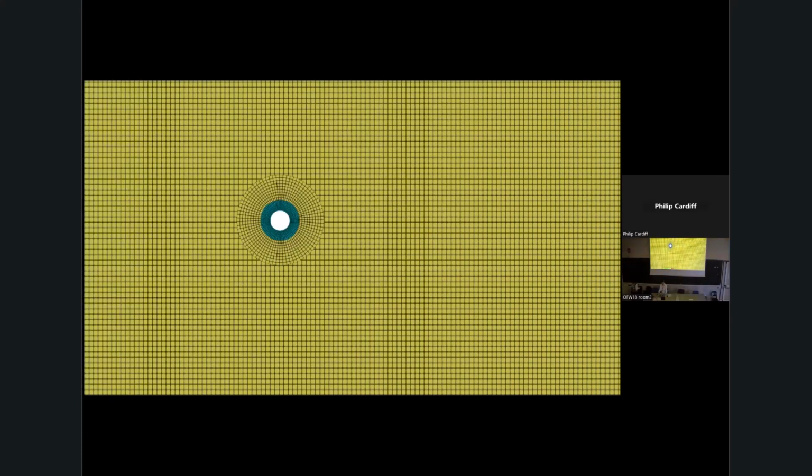Just to show an example with preCICE, and you can find this on the website, I took overPimpleDyMFoam, I think they call it. It's the overset version of pimpleFoam from openfoam.com. That's a fluid model which hasn't been ported yet to solids4foam, so I was able to directly couple it with the solids4foam solid solver.